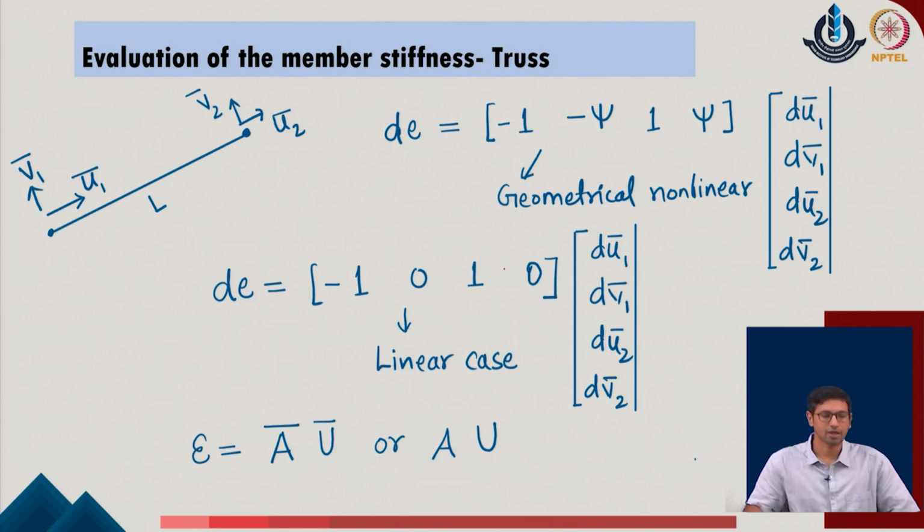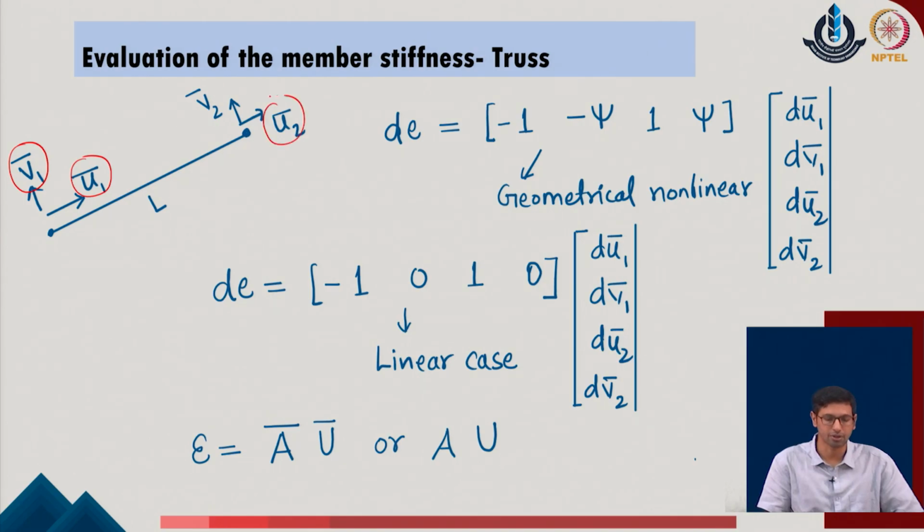So, to start with, we have one system in which we consider a simple truss member. As we have already done this part earlier in the geometrical stiffness formulation, for any member of the truss we define that in the local coordinate it has some displacement parameters identified, and corresponding to those displacement parameters the user can calculate the total change in length of the given member.